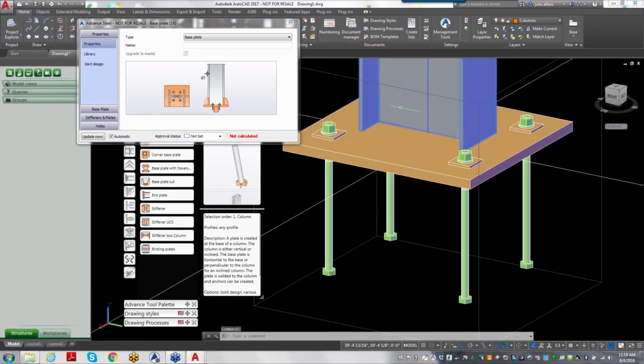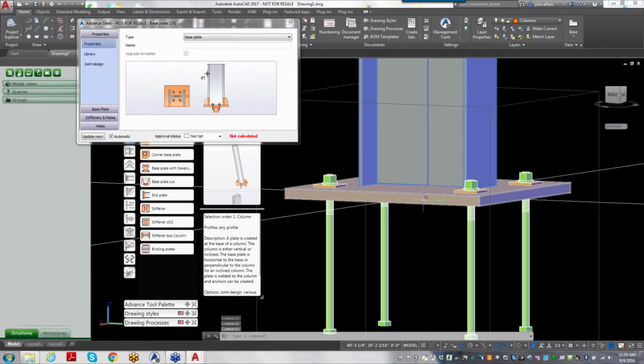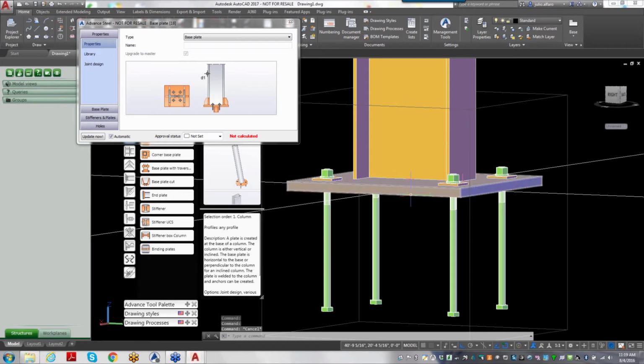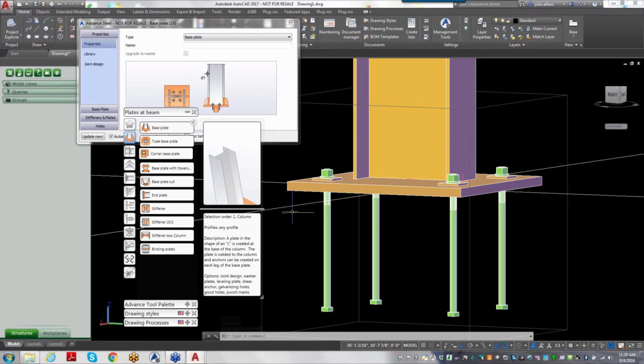It's actually cutting the column so that whatever we were at finished floor, we're still at finished floor, but it's cutting the column through that plate, okay? You have the ability to save these connections to a library. As you can see, I have Rob and Luke. I don't remember who Rob and Luke is, but I have those still saved here.